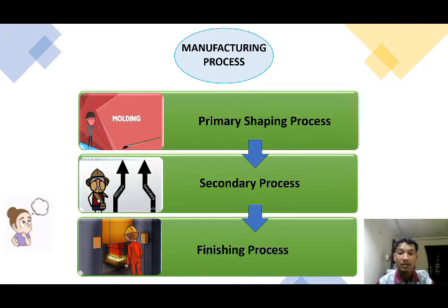The outer layer and elongate core of the earplug are shaped in a mold prior to expansion during the secondary process. Later, the elongate core of the earplug is formed by extruding the material. The elongate core is cooled and cut to the desired length for an earplug. Later, the elongate core is covered with an outer layer comprising a second material. For the secondary process, heat is applied to a portion of the outer layer. This method includes the step of extruding the first material to form the elongate core.